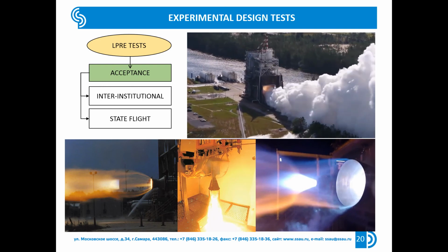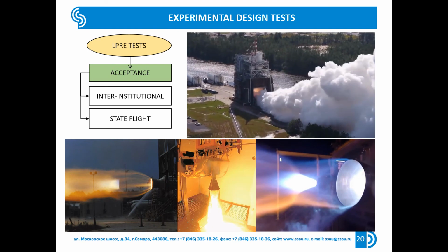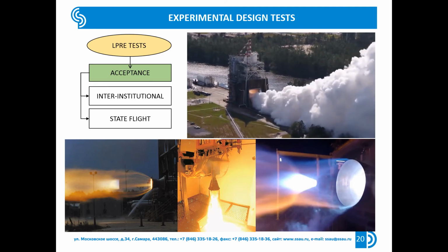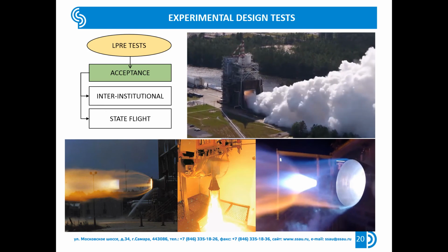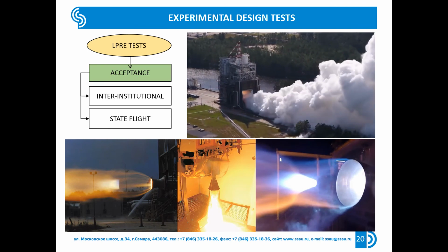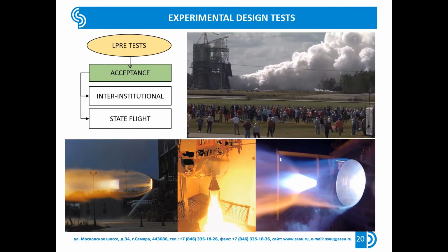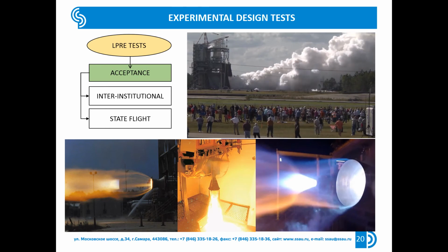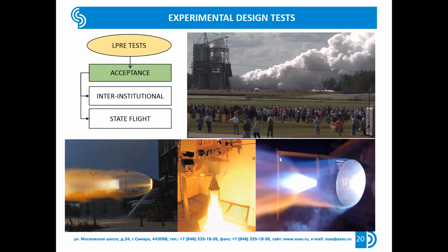Interinstitutional tests are carried out by a commission consisting of representatives of several interested organizations, the program of which is agreed with the representatives of the organizations concerned and approved by their management. This includes the carrying out of resource and special tests for external influences. A series of special tests shall also be carried out prior to the interinstitutional tests. Transport tests to confirm the performance of the LPRE after it has been transported by vehicles over specified distances. Climatic tests after long-term storage under extreme temperature and humidity conditions, etc.